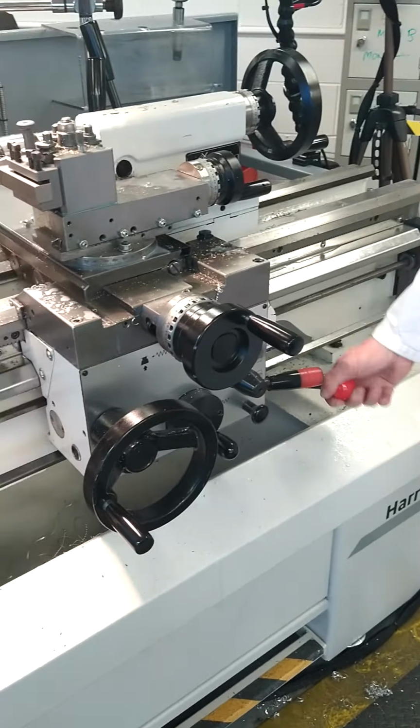So to stop and start the machine safely, it's out and up, and it can bring to a halt and brake underneath. Finally, at the end of class, it's always important to clean down afterwards, and when you're finishing up your part, to always remove back the tailstock, back to the very end, moving your carriage back to the end.